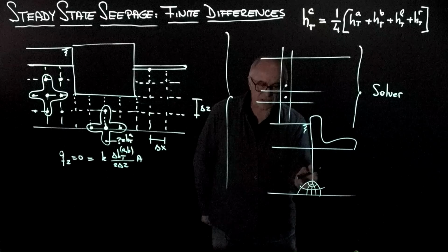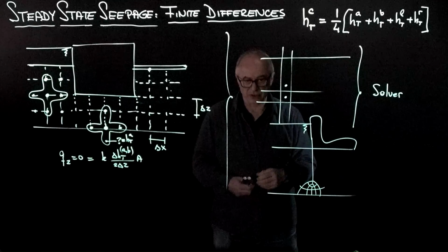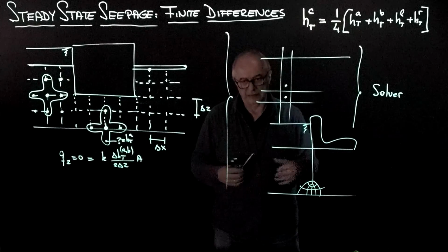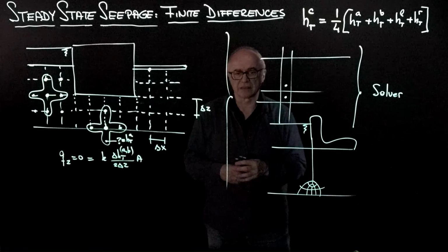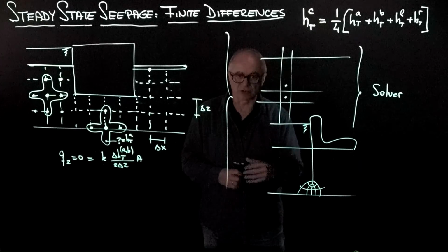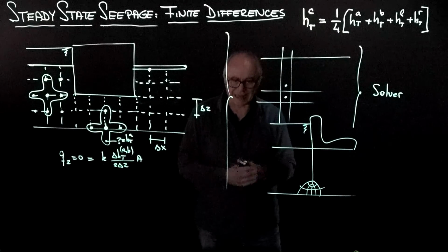So you need to resolve that with higher spatial resolution in order to properly predict the field of the total energy h total. Be careful at constrictions, equivalent to stress concentrations in mechanical analysis.